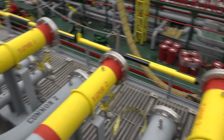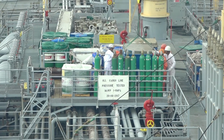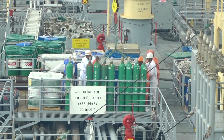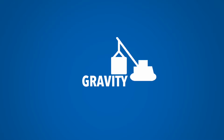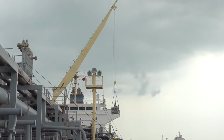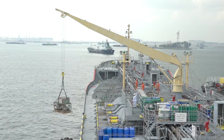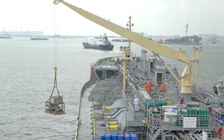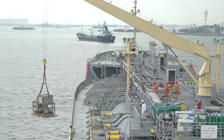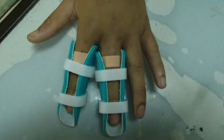For the purposes of hazard recognition, we separate energy sources into 10 groups. We will use this tool to identify hazards within each group. Gravity. Gravitational force is present all the time. Anything high up or being lifted up has the potential to fall down. This could include suspended loads, a tool used on a scaffolding platform, or items stacked too highly. Slips, trips, and falls due to gravity are very common causes for injuries on board ship.